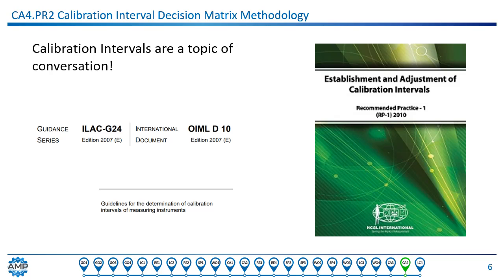Calibration interval decisions establishes a means to assign calibration intervals to instrumentation. The idea here is to achieve optimal calibration intervals. Optimal means not too often and not too infrequently, but enough to stay in calibration for the duration between intervals. And that is just about where real direction on the matter ends.